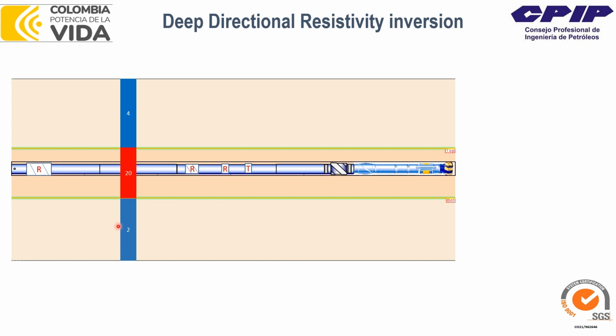But the new generation of the tool, with a depth of investigation of 30-40 meters, is not limited by that number; it is limited by 6 or 7 layers. So if between these 30 meters you can have like 7 layers, the inversion will resolve it for you. But of course it's quite difficult, and you need to have the appropriate environment, and you need to have a big resistivity contrast. That's the important point, by the way.